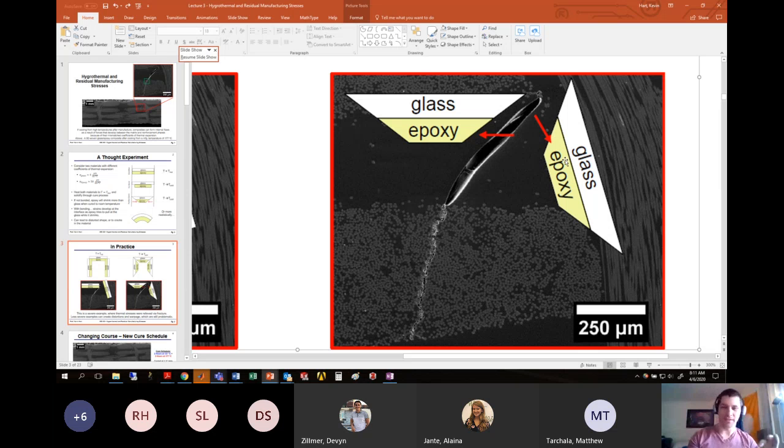And so this is a composite that has cooled down from high temperature, and this sort of pulling is occurring. And this case is particularly severe because the pulling was so severe that there was actually fracture that occurred. Those of you taking Schaefer's fracture and fatigue class know that there has to be some sort of nucleation or initiation point for these cracks to occur.